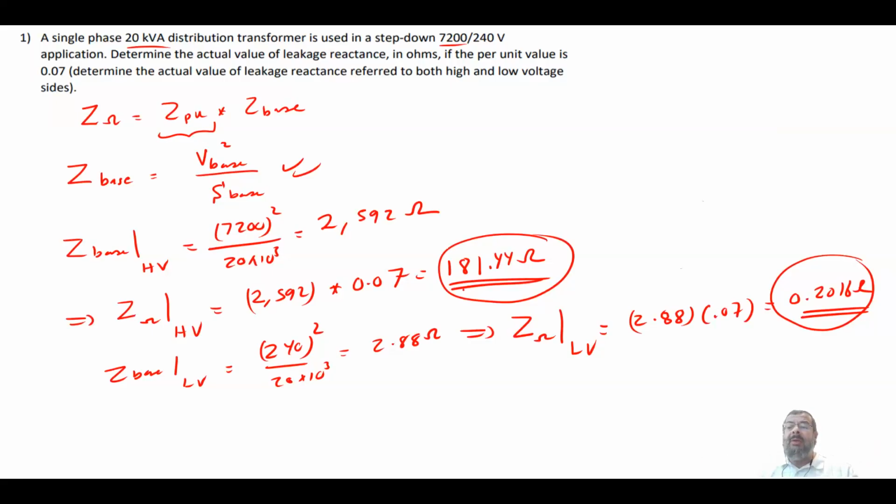The reason is that at the low voltage side, the current is extremely high. So for the I squared R loss, you want to balance the losses in the primary and in the secondary, so the resistance in the low voltage side is always much less than the resistance in the high voltage side. Keep this information in mind as we go to the second part.